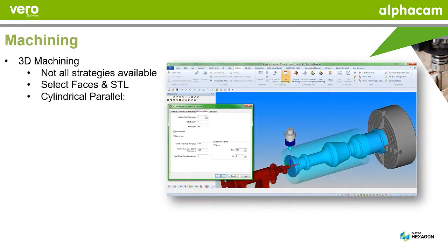We've seen some of the cylindrical parallel in the GUI modifications, and we obviously saw the extents visualization. But now regarding machining options, we now have the option regarding width of cut, where you can specify an actual value. So we see on the main dialog that we have the width of cut in degrees. Well, if it's easier for the user to actually say, well, I want a particular step over, this will then calculate the width of cut in degrees.